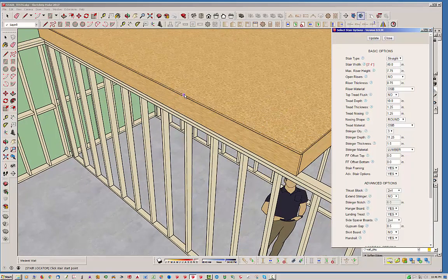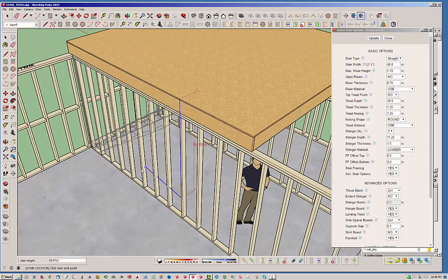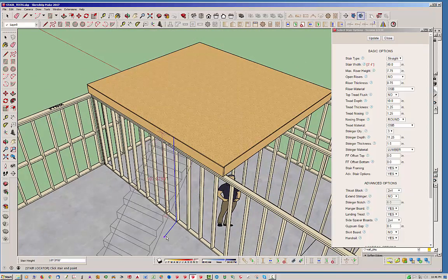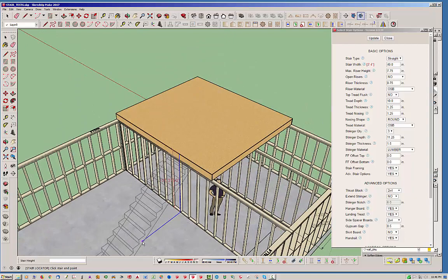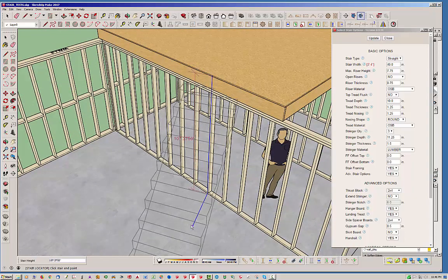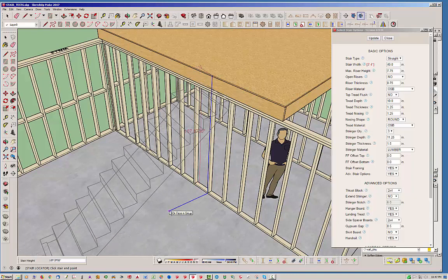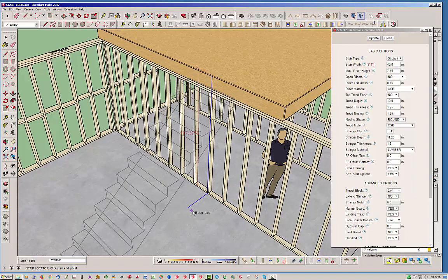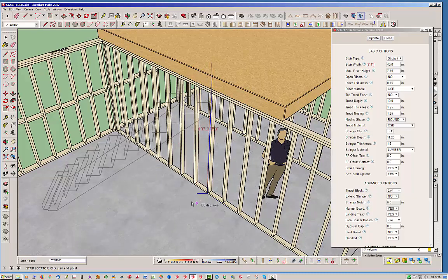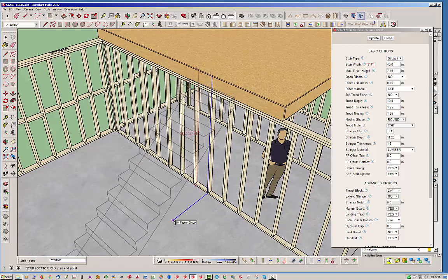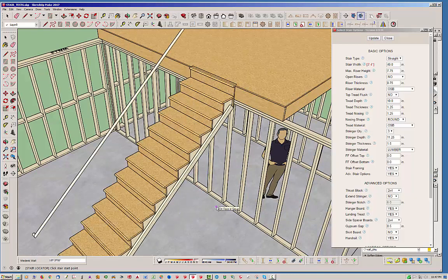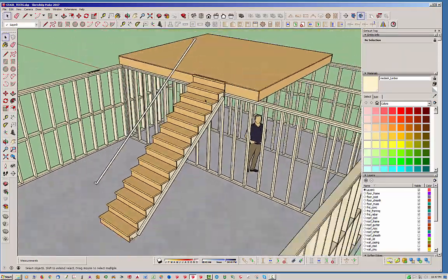I'm just going to pop a point here, and then I'm going to move my mouse out here. Let's see, keep zooming out. And you notice how this isn't locking in. I do actually need to make it so it locks to the axis, but for the time being, just hit your Control key and it can lock you to any of these standard positions, and then of course that unlocks you if you keep toggling it. Then we're going to just lock it here right to the 0 degrees for now. Alright, so there you go.